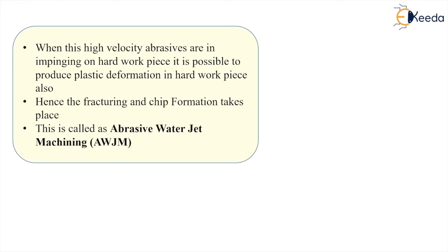At the same time, we learned about water jet machining. Here, water causes the plastic deformation and fracturing of the work surface with a high speed water jet, which can be used only for soft materials like rubber. The limitation of water jet machining was that it cannot be used for hard workpiece material. So we added the abrasive grains so that it can now be used for hard workpiece material also, and the process is now known as abrasive water jet machining.